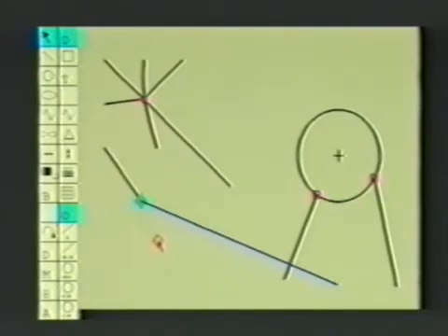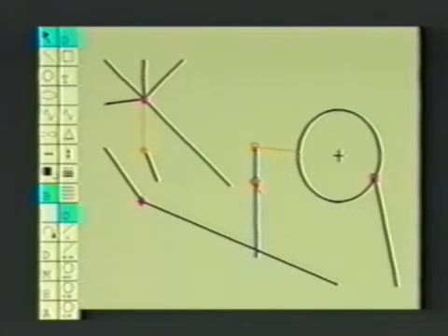The other method for deleting constraints is break mode. This mode temporarily disables constraint maintenance. The objects move freely. Broken constraints are clearly noted and removed when constraint maintenance is re-enabled.